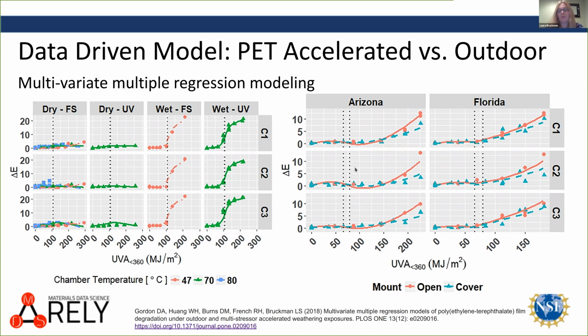What we also see when we're talking about cross-correlating and making sure that we're understanding the lifetime outdoors as well as not just under accelerated exposures, is that Arizona and Florida actually have very similar behavior. And we had assumed that Arizona would not because it's dry. But what we're surmising here is that, in fact, water sitting on these materials outdoors plays a key role as morning dew.